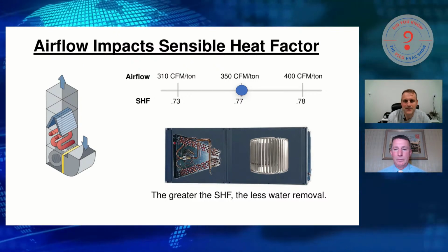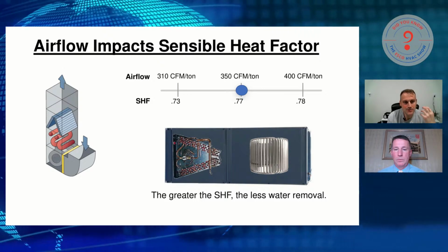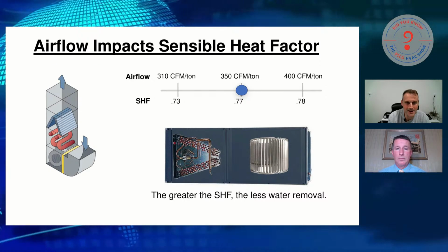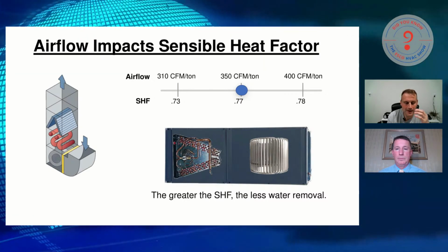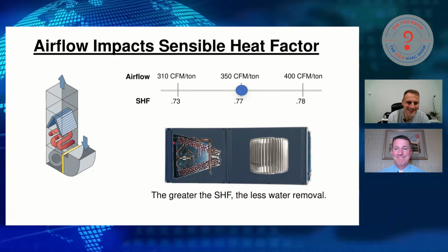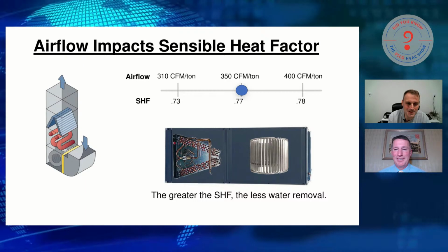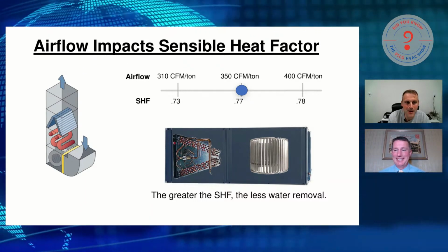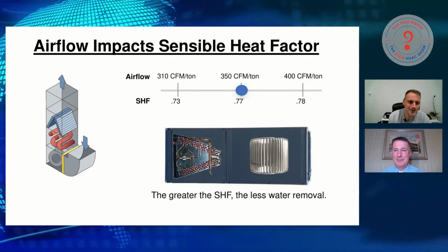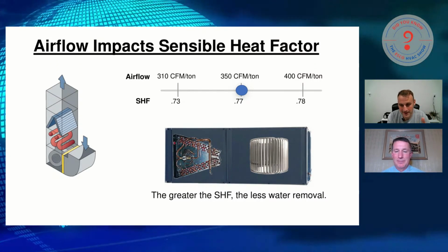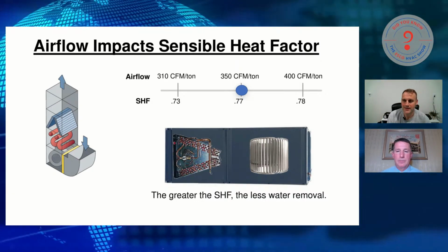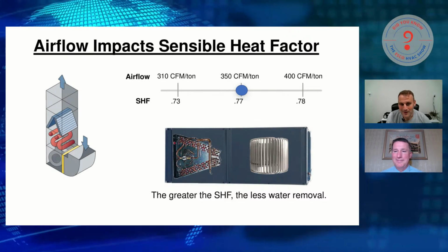This is just a little screenshot picture I'm putting there. And all I'm saying is if you walk into a home and that home is not feeling comfortable, it's muddy, there's too much moisture in the air, could it need a full-blown investigation? Yes. But would I start checking airflow? Yeah, I probably would. I'd want to make sure that I'm not moving way too much air and leaving a whole lot of moisture removal capacity on the table that the air conditioner could be doing for me. That's where I'd go with it. And if it's already there, at least I know in my mind it's where it needs to be. And then I take it to the next step. So that's my spiel on why we should measure airflow.